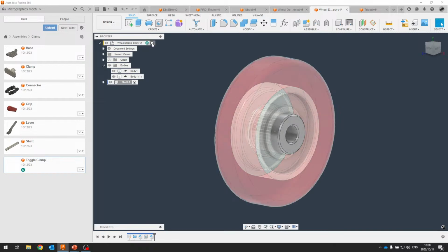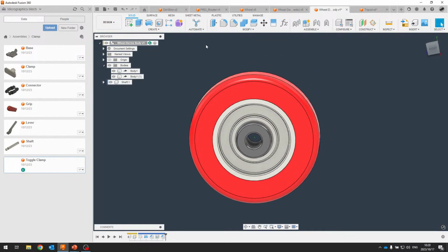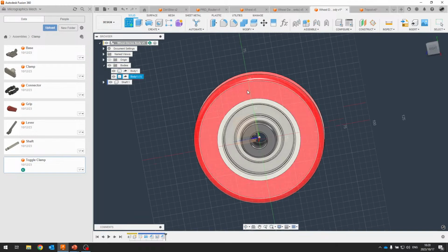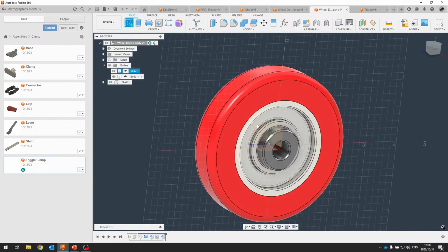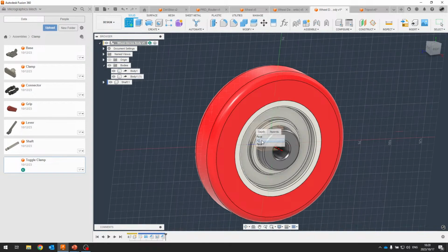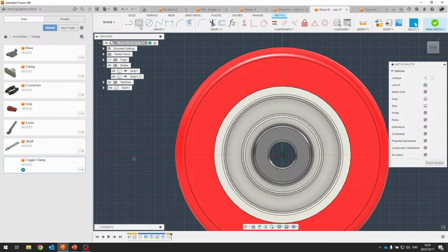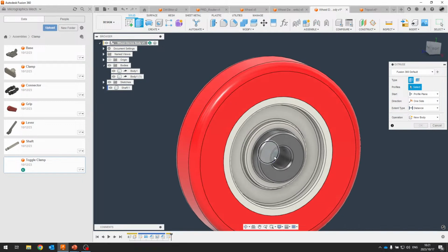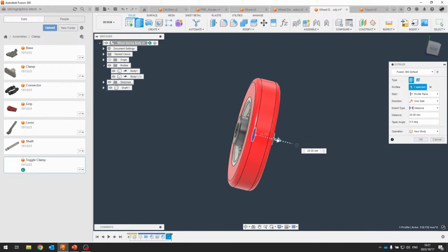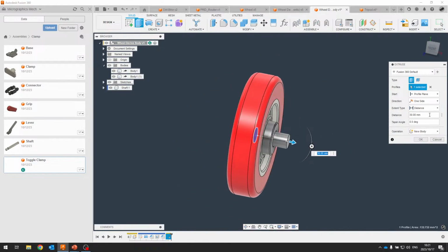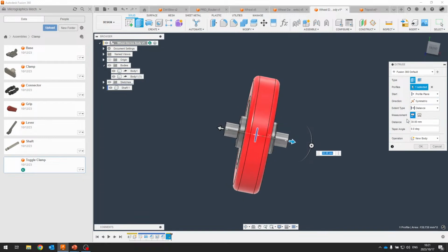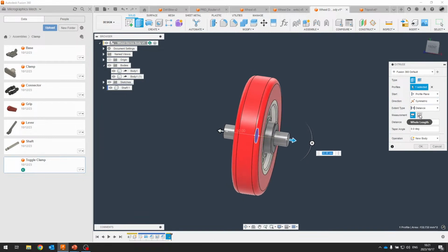We'll do this one more time, just very quickly. Come back to the main assembly. I'm going to create a new sketch. I'm going to just be a little bit more clever about this one. I'm going to create it in a side view, and this allows me to then just project in that internal diameter and extrude that symmetrically. A lot quicker and easier. Let's go, whole length is, let's say, 50.